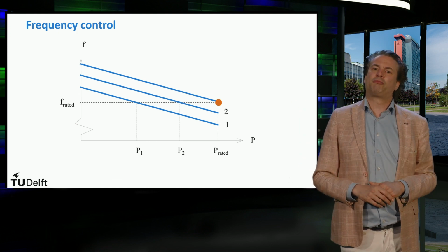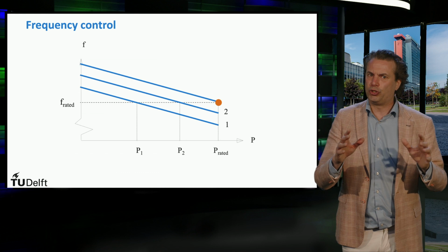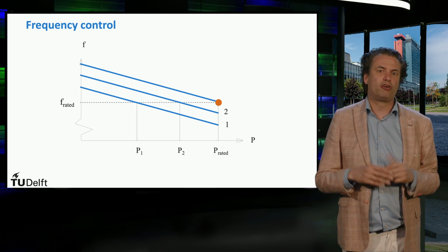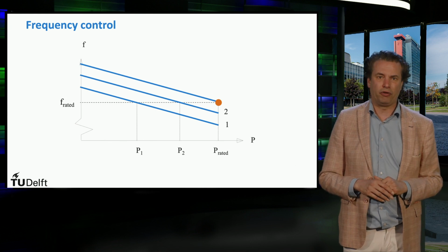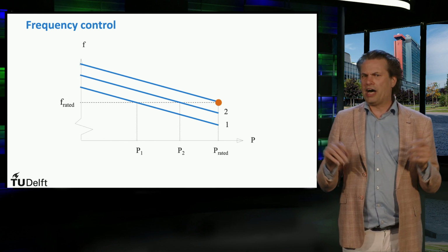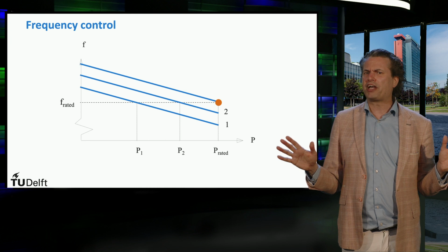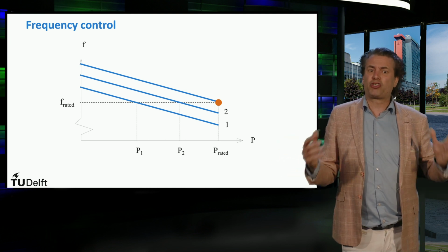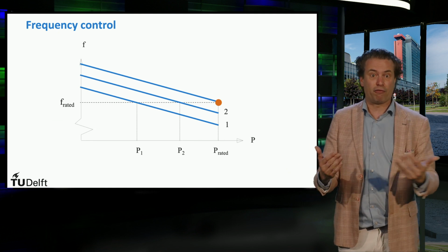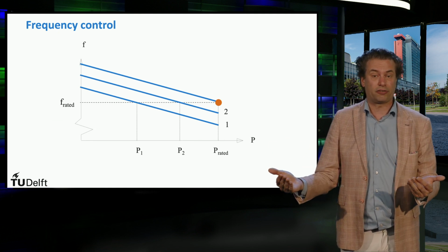In the figure you can observe how the secondary control is used to modify the setting of the speed governor in such a way that the frequency is brought back to the original reference. Now we understand how the power and the frequency of an AC power system is controlled. In the next video we will discuss what this means for the integration of photovoltaics in an electricity grid.